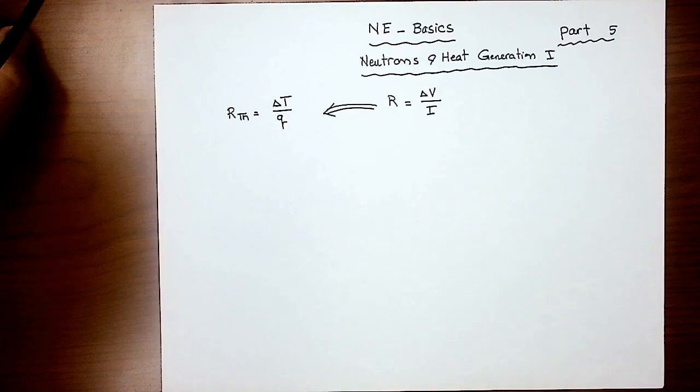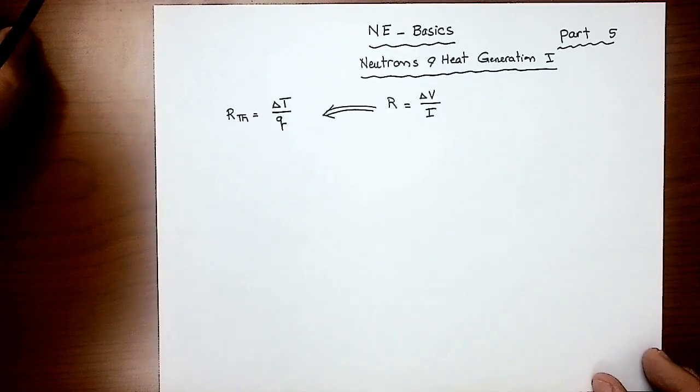Then we have shown that if you have a plate type fuel, cylindrical type fuel, spherical type fuel, we have introduced different types of thermal resistances that we have to use specifically for the nuclear fuel. Everything beyond nuclear fuel, like the gas gap, the cladding, the coolant, we go back to the thermal resistance without heat generation. So we covered that in the last few recordings, and we were able to make a summary table showing all these kinds of resistances.